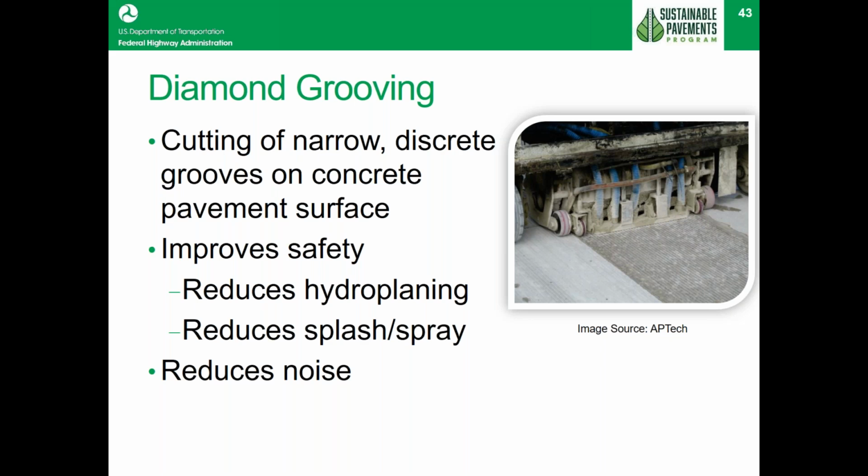Okay, so I talked about diamond grinding a few minutes ago. Now we have something called diamond grooving. Is this a little bit different? It really is, because it tries to deal with a different problem than the grinding did. Grinding was supposed to address those pavements that were not very smooth for some reason. And the diamond grooving tries to address the other problem, when pavements get too smooth from issues like aggregates polishing, or where we have some safety issues for some reason or another.